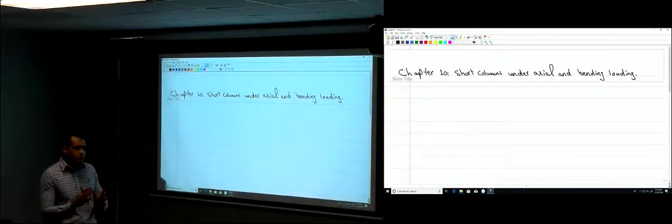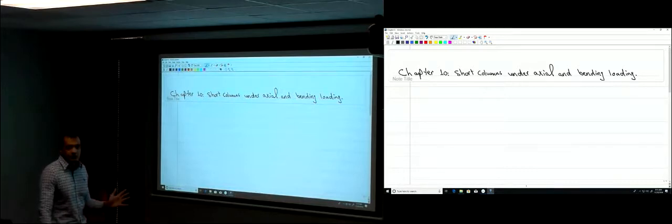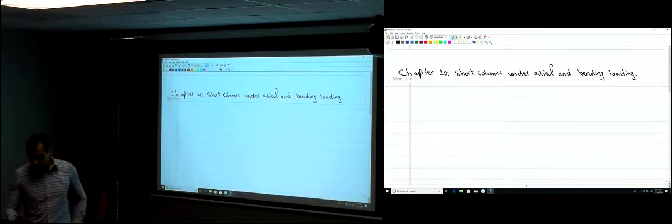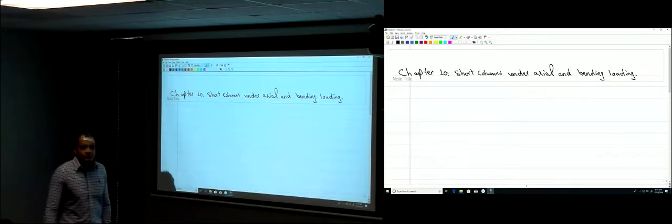The axial load is distributed among the concrete and the steel, and you have the factor of safety phi, which is 0.65 or 0.75. 0.75 when you have spiral stirrups, or 0.65 when you have regular ties. And there is the factor of safety alpha to account for accidental eccentricity, if there is some eccentricity due to problems with construction.